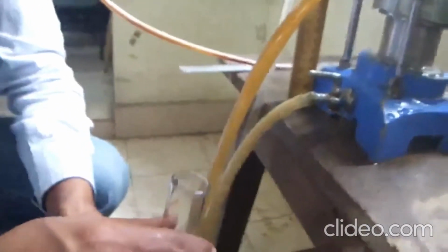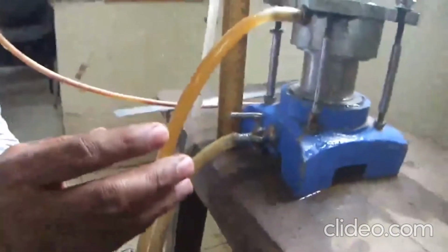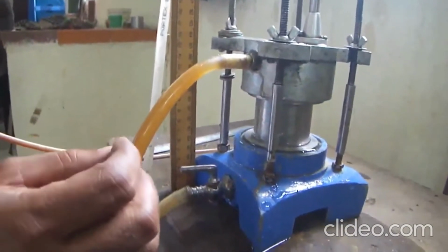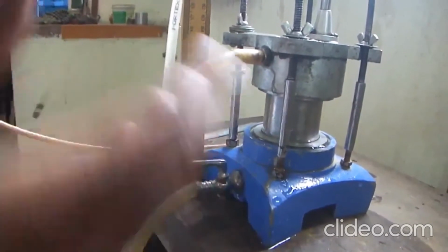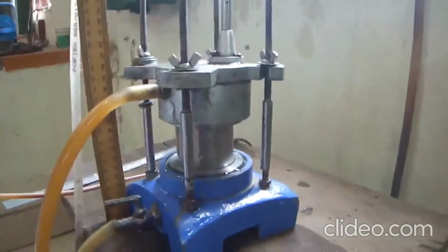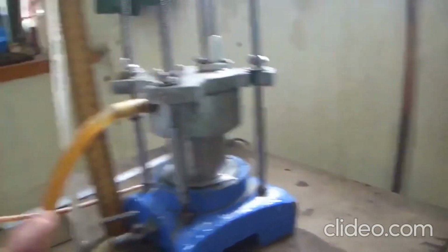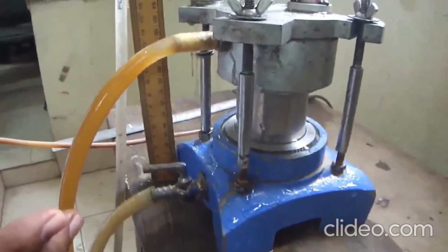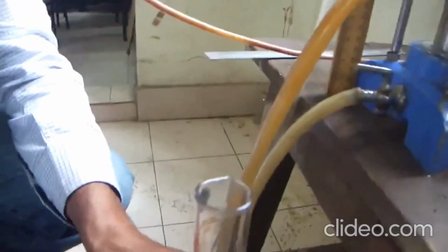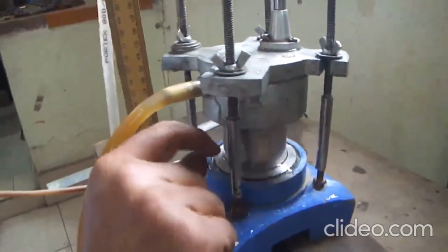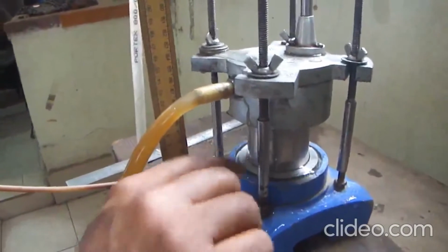So we need to measure the amount of water that is coming out from this sample in a particular time, that is delta T. We can take 2 minutes, 4 minutes, 5 minutes, then increase the time to measure the discharge, that is Q. That is basically, if you have come through earlier, or what I told, K is equal to Q by A times delta S by L. And for a certain amount of time T, and this area of this sample we have taken, that is 5 centimeter in size.